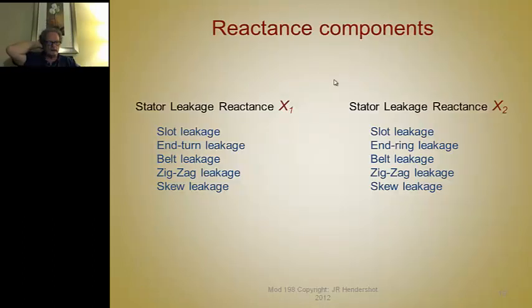The reactance components are the most difficult things to calculate, and there's been many famous motor engineers down through the years that have come up with their own methods, with what sort of calibration or fudge factors they use for different kinds of machines and different shaped bars, that helps them to calculate the leakage reactance. Let's see, I believe they're both stated. This should say rotor leakage reactance here. That's a mistake, so cross that out and let's call that rotor leakage reactance.